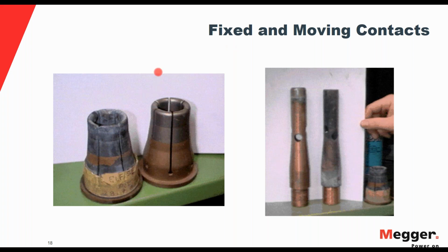And this is an actual case of what I showed you earlier from a breaker. Once they opened a breaker, they found out that the contacts had worn out after a huge short circuit current. This was, I believe, a generator circuit breaker case.